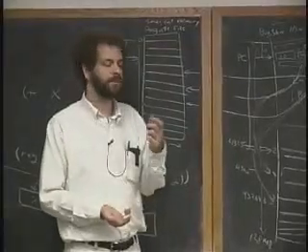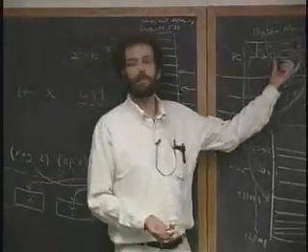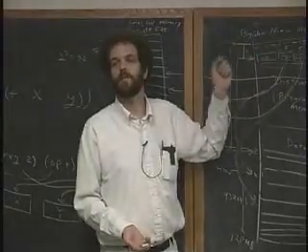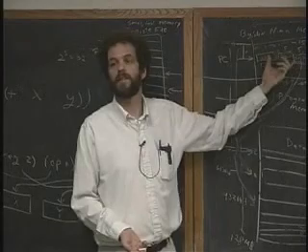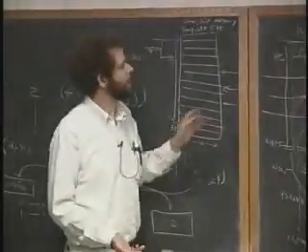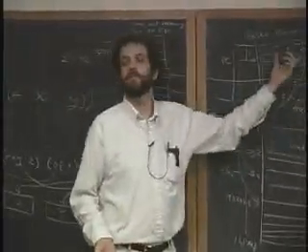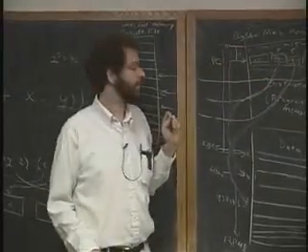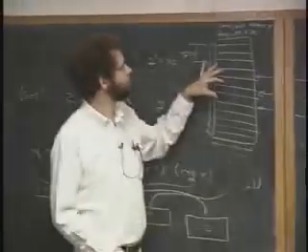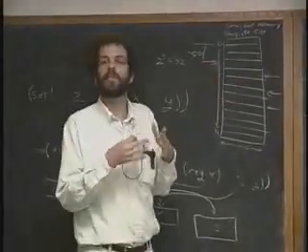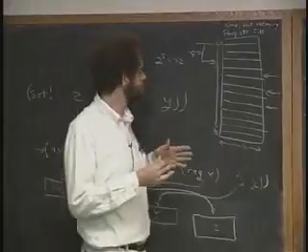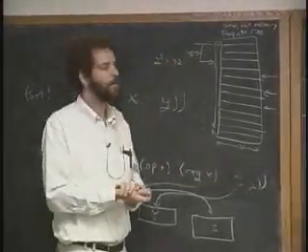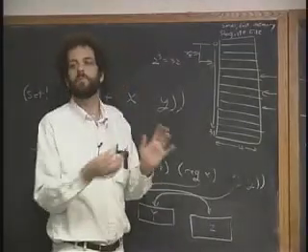But there is another reason having to do with the efficiency of these opcodes. So let's say actually that these were 10 bits wide as opposed to 5 bits wide, or just making this thing a wider word, right? Having more registers. Because, of course, if this word is wider, then we can fit more stuff in there. The question is, are you using those bits well? And the answer is that there's an idea of how many registers your program tends to work with at any given time. And past a size of 32 or 64 numbers of that order, it turns out that you don't work with more.